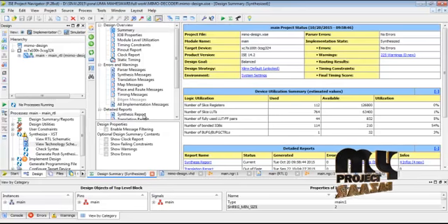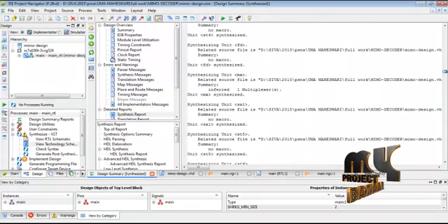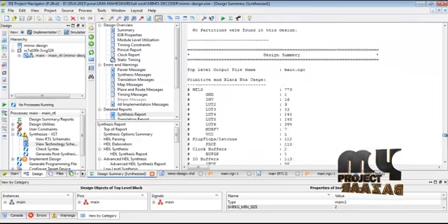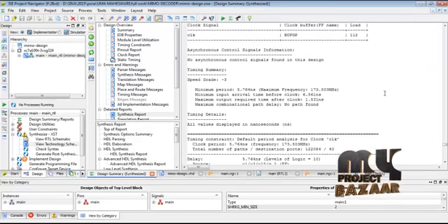Then to calculate the design summary for synthesis report. This report generates what are the logical blocks to be presented and the flip-flop paths to be present in the overall device utilization summary results, and to calculate the timing summary results for overall MIMO detecting architecture.